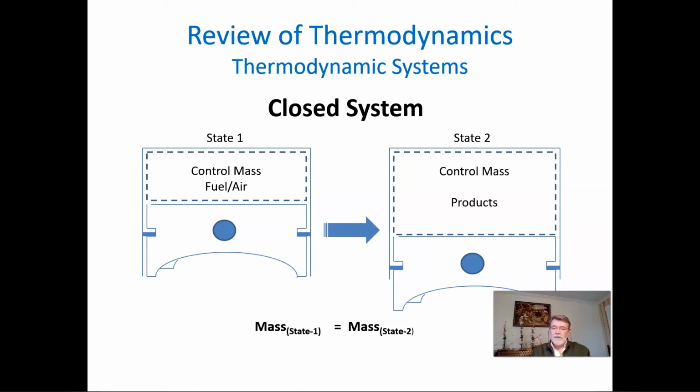No, because we are not exhausting yet, right? So the mass inside of the system is still going to be the same as the fuel and the air we originally put in the engine. So that means that mass flow wise, when you actually do the exhaust, whatever the mass of the air and the mass of the fuel you have coming into the engine, you should have the same mass flow of the exhaust coming out, just like we saw during that Excel analysis, right?